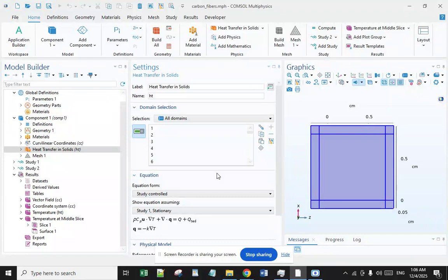This simulation reports the thermal behavior of plain woven CFRP composite using simulation at the micro, meso, and macro scales. The TC was predicted numerically and compared to experimental findings and analytical models. Good results were found using the approach of multi-scale modeling. A parametric study was carried out to analyze in depth the influence of certain variables on thermal properties.